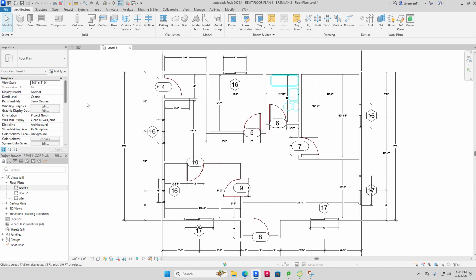So go to level one. Now to put in a floor, we've done this a couple times. We're going to put in a wood floor here, and we're going to actually make it go from the outside. We want it to go to the outside wall, all the way around, so it doesn't just go to the inside. You want it to press out to the outside like it's on a slab.